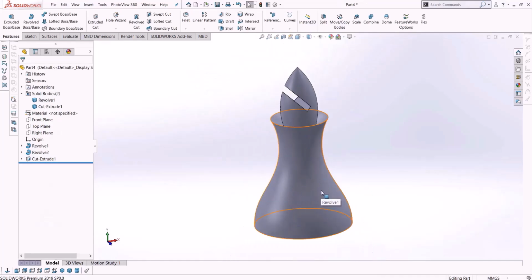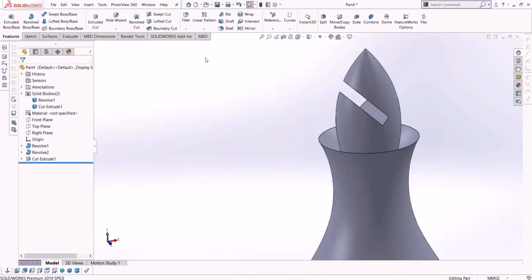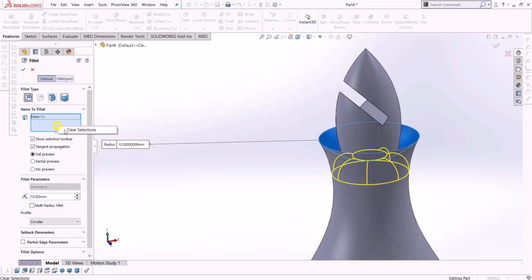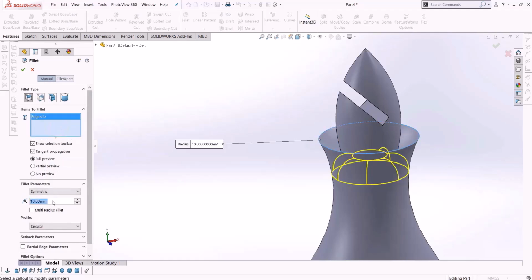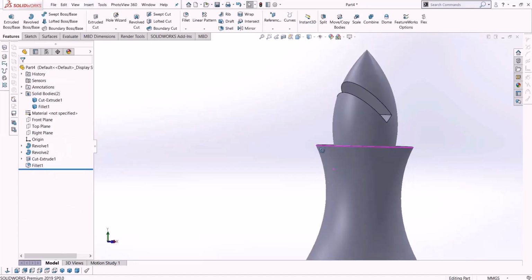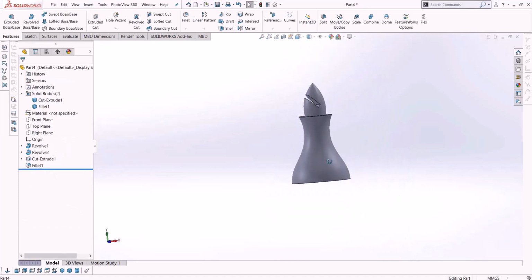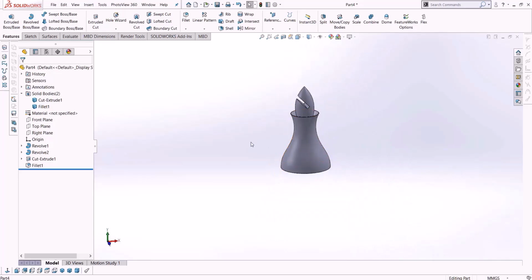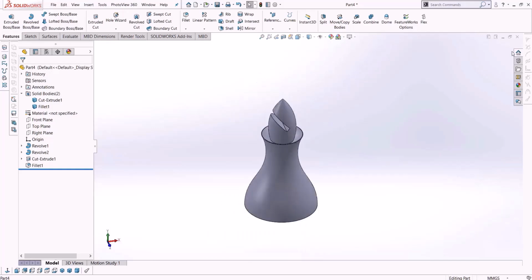Now it has become very minimal, almost to the point of being simplistic, and we could have created some additional shapes on the edges as well, which we did enough in the previous step where we focused extensively on edge detailing. Let's select this edge and give it a small fillet here, like 3/10 of a unit, which is a subtle rounding that enhances the overall design. Now we have other tasks to do, which will further refine and complete our project. Now, as a single piece, it might not be very interesting, but if there's a whole family set of these, like a knight, a bishop, a king, and pawns, it might perhaps find its own place.